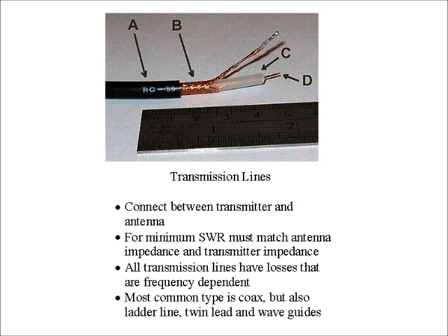Here's the other part. What you'll find is that if your antenna is at a different frequency than its half wavelength, it's not going to be 72 ohms when it's a half wavelength above the ground. It's going to have a higher impedance or a lower impedance. And what that causes, remember we're talking about this SWR thing? And why do we care about SWR? Protect that expensive transmitter.